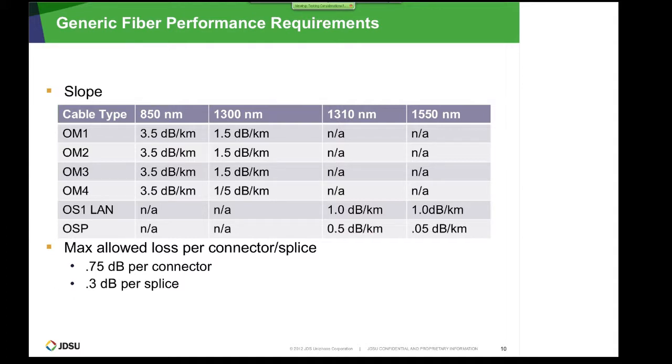Yeah. Okay. What is very important to keep in mind is that up to now we were speaking about full fiber. It is necessary to take into consideration that each fiber has to be terminated with an optical connector. Also, in some cases, fibers have to be spliced together. It means you should take into consideration that there is a limit of 3/4 of a dB per connector. This is a maximum limit. The ideal or good optical connectors should have insertion loss of about 0.5, even less. I would say the good connectors nowadays have insertion loss of 0.25, 0.3, and in the case of splices, good splices are somewhere around 0.1 dB per splice. Keep in mind, I'm speaking here about multi-mode, not about single mode fibers.